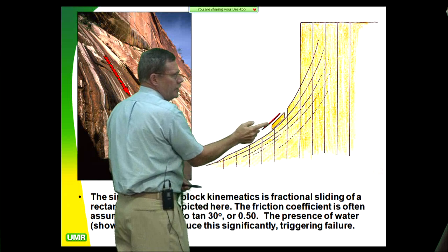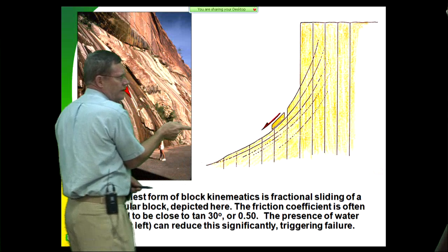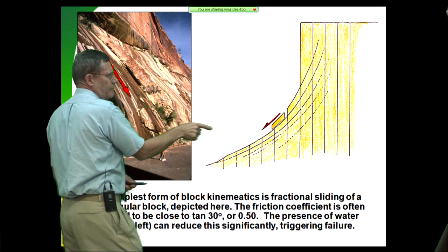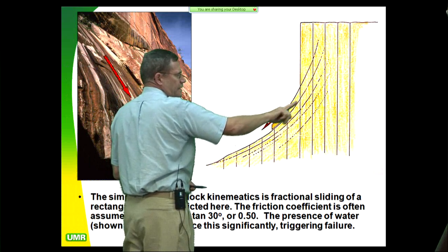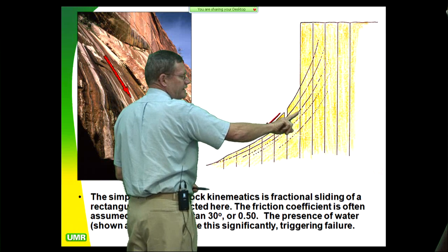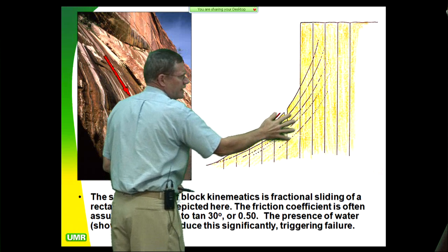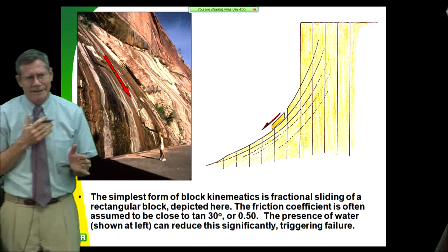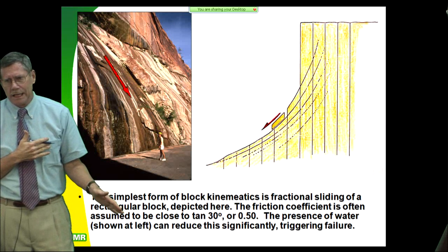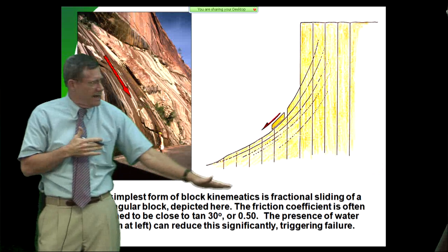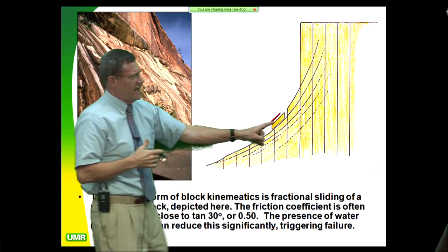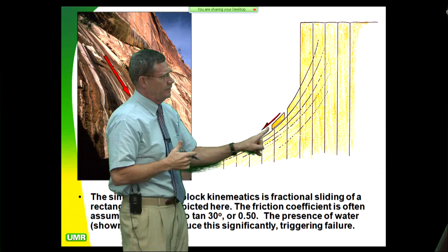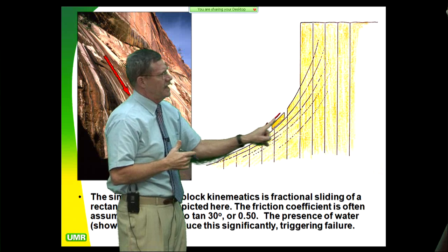Okay. You noticed if I sit over here with a LiDAR rig, I might pick up some of this, but not all of them. These curvilinear joints have a terrible inclination. They're right at tan phi. And so they're going to slide out at the slightest amount of pore pressure buildup along here. These things are just going to slide right on out.